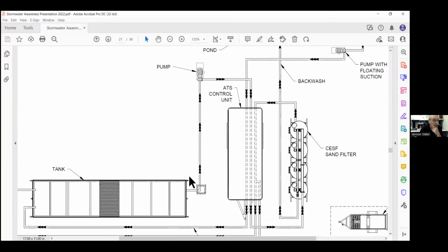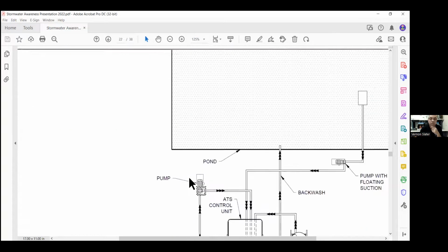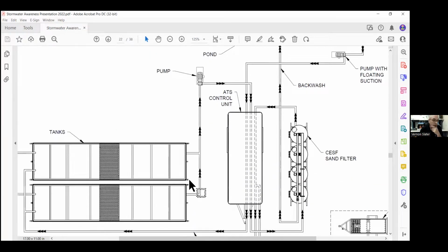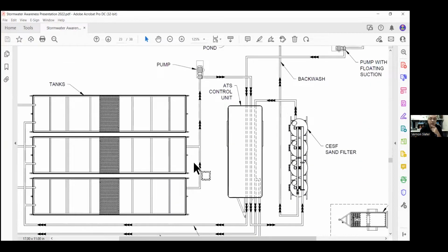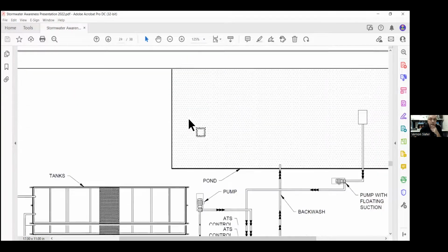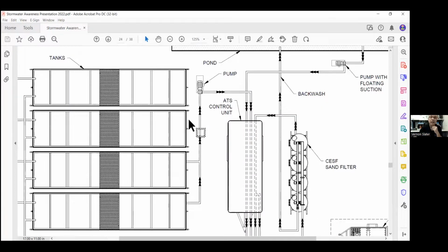For each additional 200 gallons per minute added, add another tank, you're going to need about 400 more square feet. And then once again, add another tank, add another 400 square feet to your pad. And for the final tank at 800 gallons per minute, every once in a while, you can squeak out using tanks to 1,000 gallons per minute. That will work. But when it starts getting over 1,000 gallons per minute, or for multi-year operations, basins rather than tanks start to make more sense.